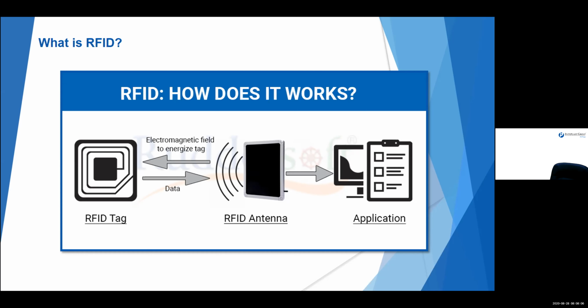By the way, according to the identification distance, RFID can be divided into several frequency types. When the frequency is high, the wavelength is short, which means RFID can be identified more accurately. When the frequency is low, the wavelength is long, so RFID can be identified in a big range. So what type of RFID you use depends on what identification range you need.